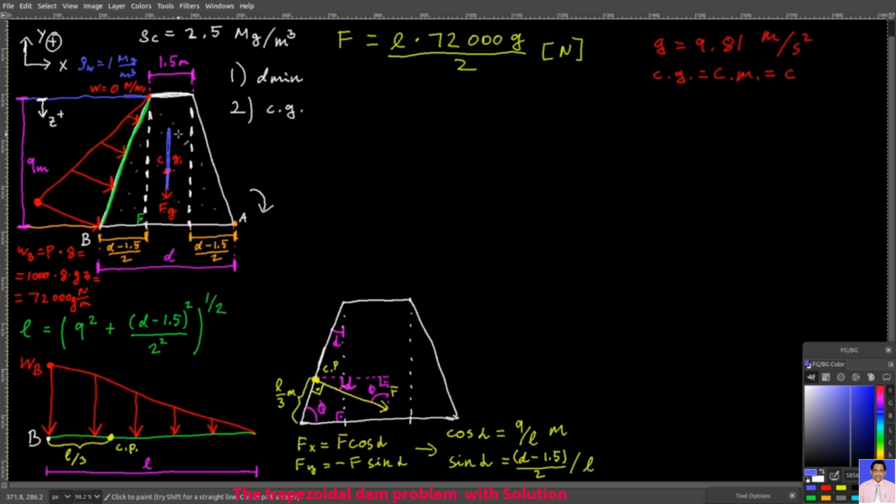But we don't need this specific point to compute the moment about point A due to force of gravity. That's because wherever the center of gravity is on this blue line, the moment arm from this vertical axis till point A, it's d over 2 meters. So the total width of the cross section is d meters, and this is d over 2 meters. And that doesn't change whether you are here or a bit above or a bit below. The moment arm is always d over 2 meters. So you would always get the same moment.